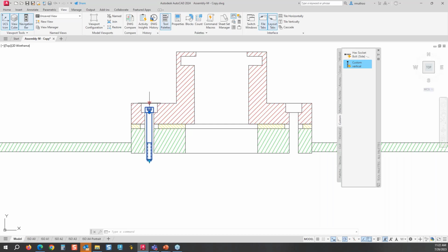So we can go on the list grip and click on it, and then maybe choose M10, because right now it's M8, which is the size of that block. Maybe M10 is the standard bigger size. So if we go M10, it looks really good. But then let's go M12 and see if that might fit better. And I think M12 looks better and it fits better.